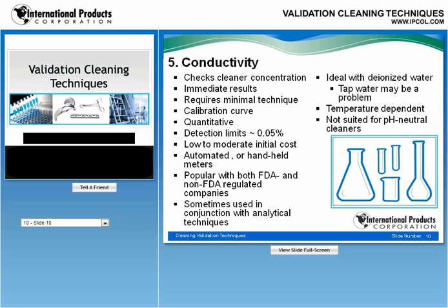Conductivity validation techniques are popular with both FDA and non-FDA regulated companies. We find that FDA-regulated companies may use this technique as a primary evaluation of the cleaning concentration, and then if this concentration exceeds specifications or control limits that they've established, then they may refer to another more analytical cleaning validation technique. There are some drawbacks with conductivity, however.